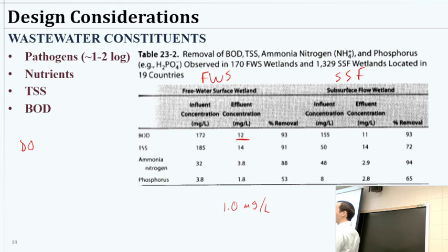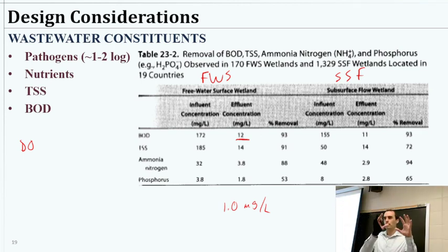If water's going through that sandy loam stuff and having that area to sediment, it's going to be a lot different than flowing through a gravel bed, right? Flowing through the gravel bed will provide lots of opportunities for sedimentation to occur within those pores, but you're not going to have as much absorption as you would if a significant amount of your water is going through that sandy loam material.